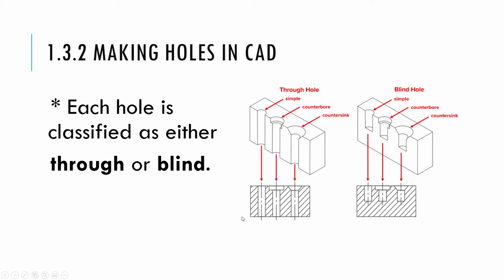You'll notice over here in the drawing, they've got a slice out of it so you can see the different kinds of holes and you can see the cross section. The part down here in each of these images has a cross section view. That's like taking a slice, a section view. And if you notice, there are these diagonal lines, and that's basically saying, hey, this is the material that I've actually had to cut through for you to be able to see these features on the inside. The other thing you'll see is these center lines. It's a long part, a little short dash, and a rather long part. Those are center lines to tell you where those center points are.